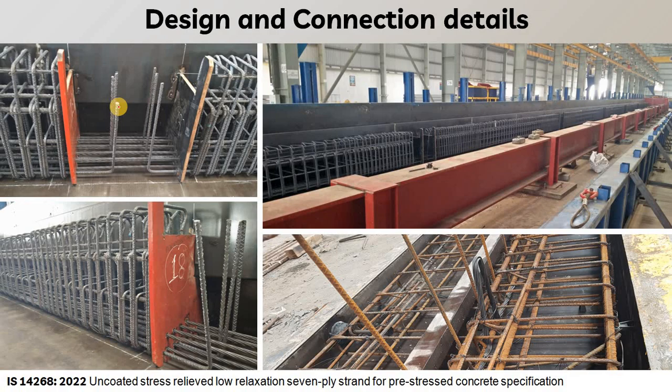So here you can see it is very important to provide the L bar to connect this beam with other elements such as the column. The column reinforcement and beam reinforcement have to be tied up to provide the structural requirements.